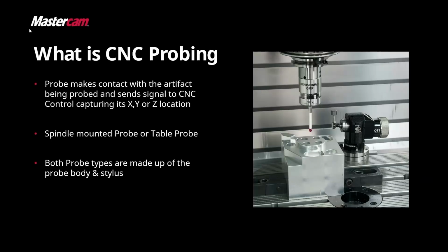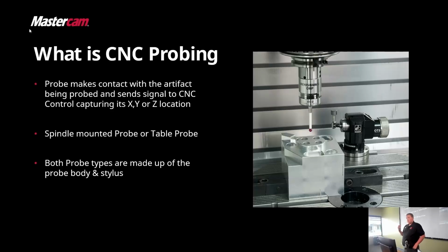So for those that maybe aren't familiar with what probing is, obviously there's going to be a spindle probe and a table probe. The spindle probe itself is just capturing a position. There are macro programs on the CNC control that do all the calculations as part of that. There's the body of the probe with the sensors and everything in it, and then of course the stylus, which is actually making contact.